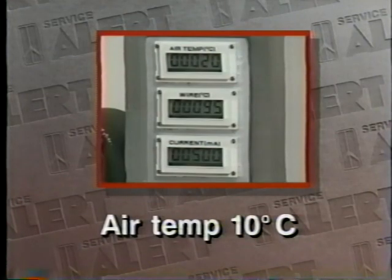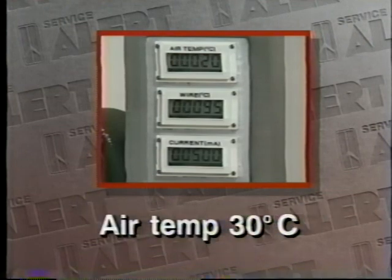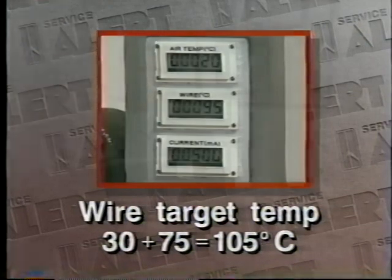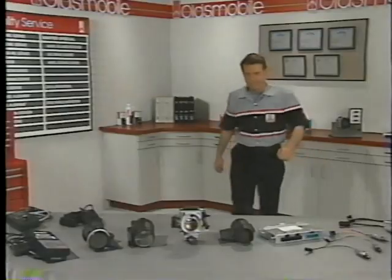If the air temperature dropped to 10 degrees Celsius, the MAF would decrease the wire heating current to attain a wire temperature of 10 plus 75, or 85 degrees Celsius. If the air temperature increased to 30 degrees, the MAF would increase current to attain a wire temperature of 30 plus 75, or 105 degrees Celsius. So, as the MAF sensor operates, it generates and monitors this constantly varying wire heating current. The sensor converts that information to a digital frequency signal the ECM or PCM can use.